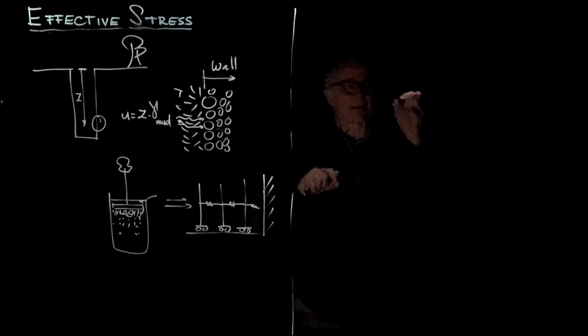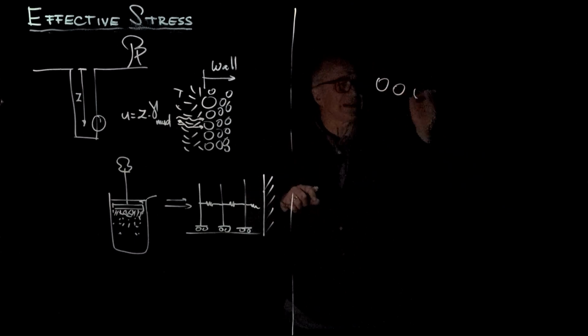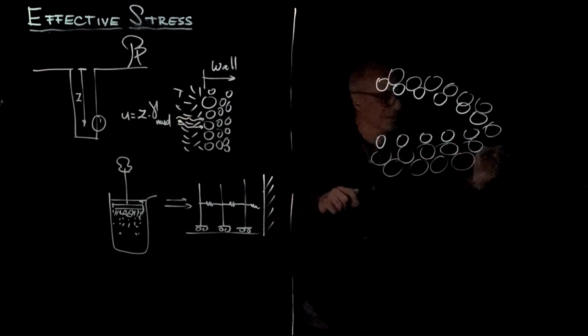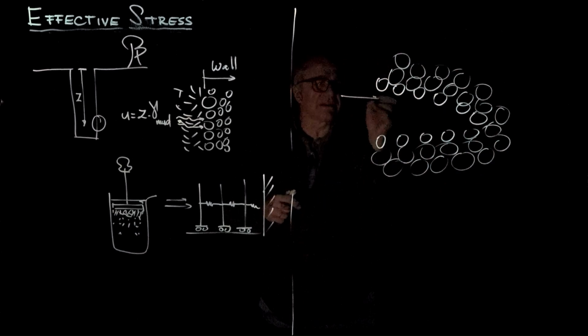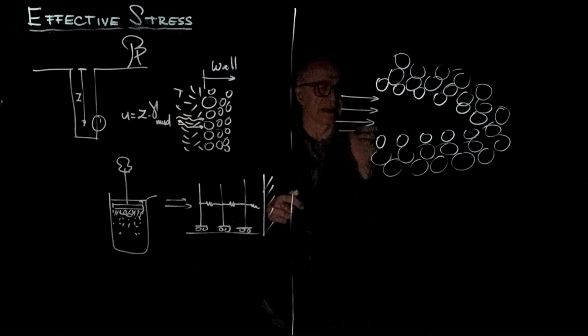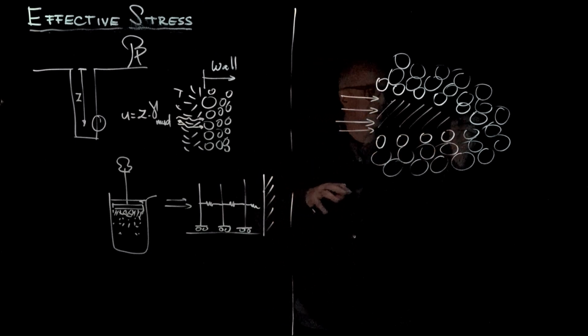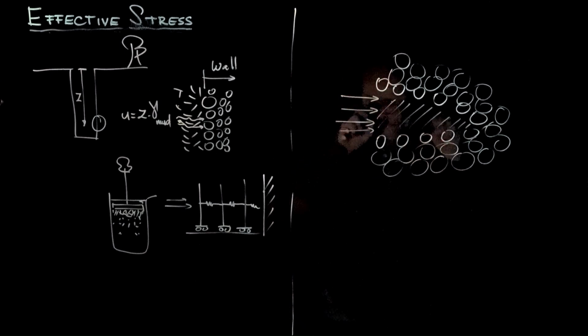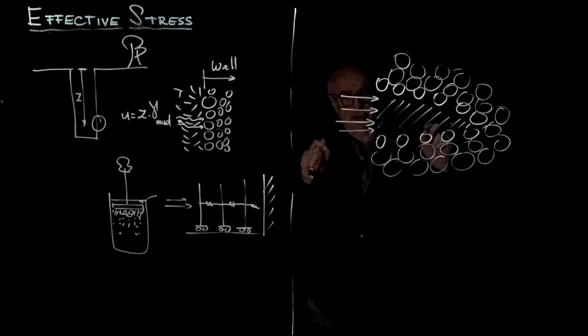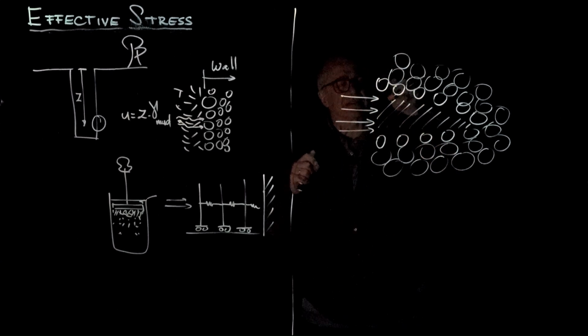So let's assume that the hydraulic fracture is taking place. Let's take a snapshot. And so these are the grains. And here is the fluid pressure as it advances. So all this cavity now is filled with fluid. And we just took an instantaneous picture. But it's difficult to visualize in 2D because contacts in 2D really are not happening in 3D. So there are all these tortuous paths.